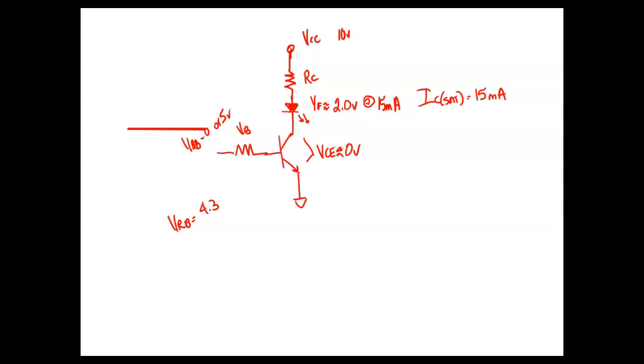It's a series circuit, guys, and this is what you're trying to see. This is less complicated than it seems. If I go back into DC and I say, okay, I've got 2 resistors here, well, actually I've got 3, but the transistor we're going to saturate. So I basically have 2 resistors. Here's RC, right? I'm giving you the diode. This guy is going to drop 2 volts at 15 milliamps. And up here at the top, I'm applying 10 volts.